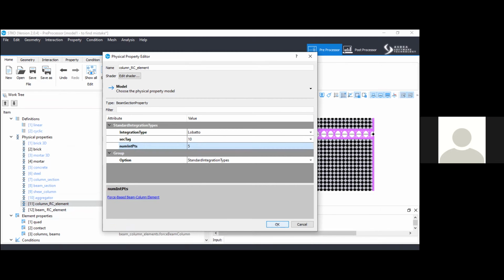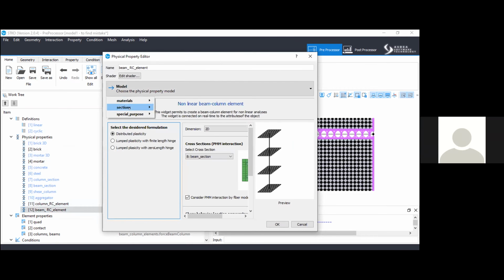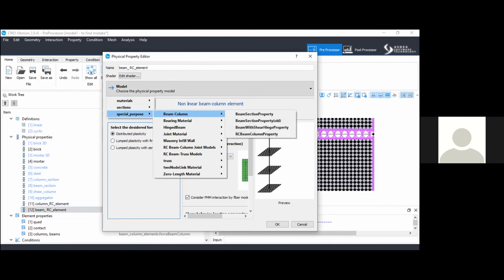Okay, good. The only thing you cannot do, which I think the tool gives you the possibility to do, is define the distance of the integration points. No, you can arrange it and then define the section between 2 specific points that you want. But if you have more points, unless you have very tiny elements, you will not have a problem. With more points you will have more results. Maybe your model will be a bit heavier, but as I said, you can just lower the integration point number. 3 is the minimum that you need to use.